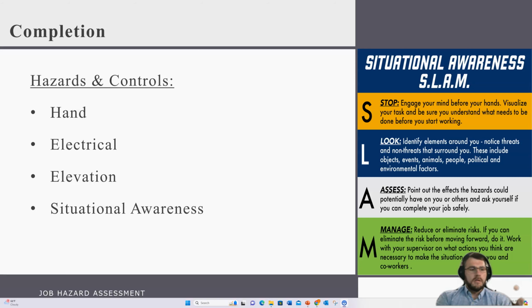We're going to utilize arc flash protective shirts and pants, safety boots, safety glasses, hearing protection, 12-calorie balaclava, and face shield to prevent accidents and injuries in case the arc flash occurred. And we're also going to use rubber insulated gloves and rubber protective guards to prevent shock.